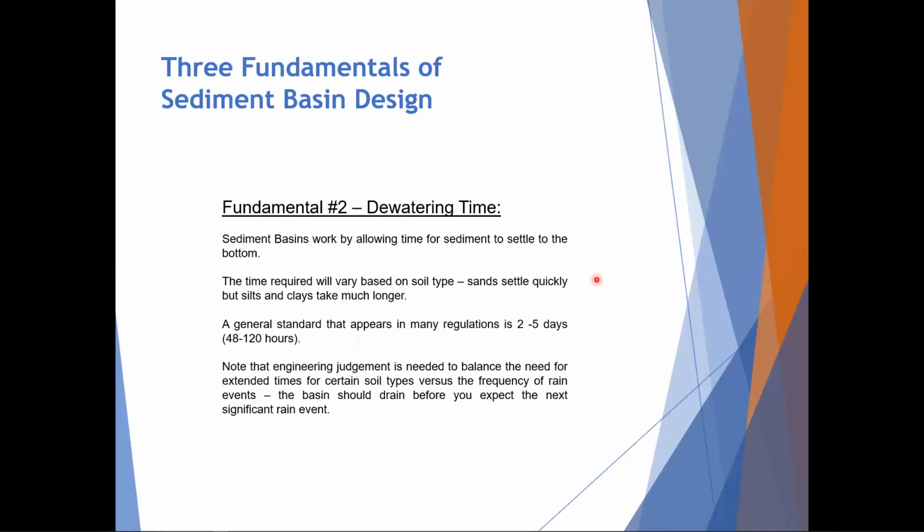So fundamental number 2 is dewatering time. All sediment basins work by allowing time for the sediment to settle to the bottom. The time required will vary depending on soil type. If you're in a sandy area, obviously it'll settle out quickly, but silts and clays are going to be much more reluctant, take much longer if they settle at all. You're likely to at least have some discoloration even after a week or 2 of settling.